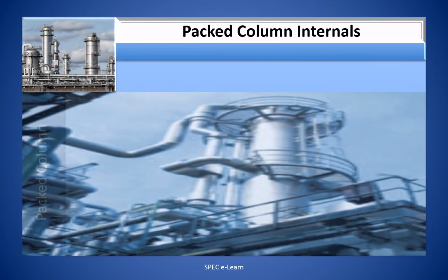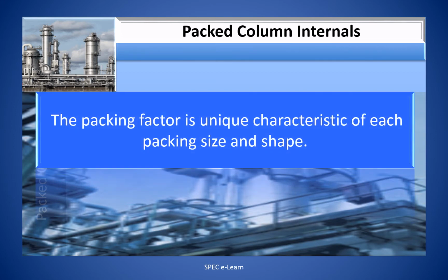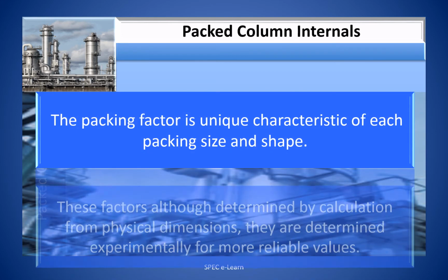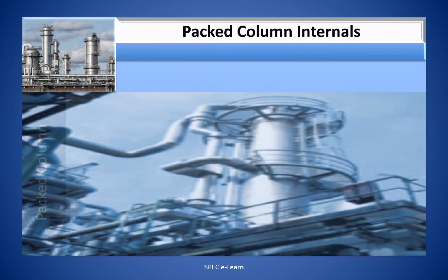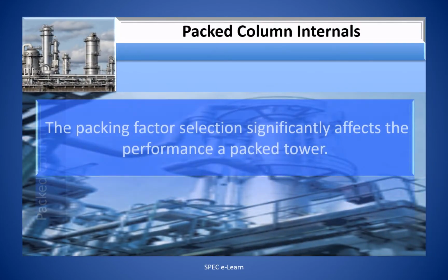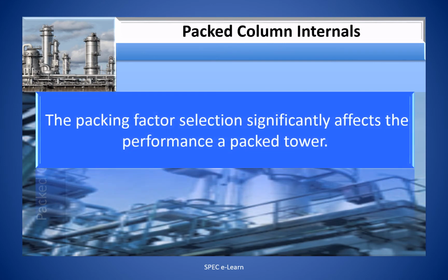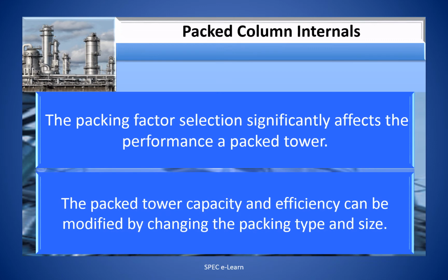The packing factor is a unique characteristic of each packing size and shape. These factors, although determined by calculation from physical dimensions, are determined experimentally for more reliable values. The packing factor selection significantly affects the performance of a packed tower. The packed tower capacity and efficiency can be modified in an existing column by changing the packing type and size.